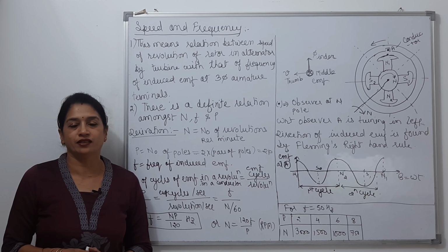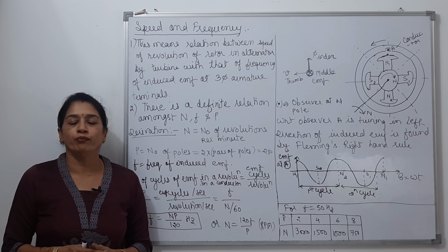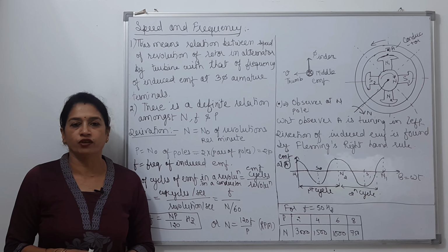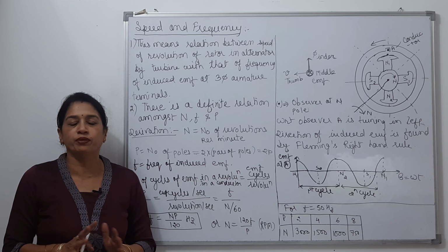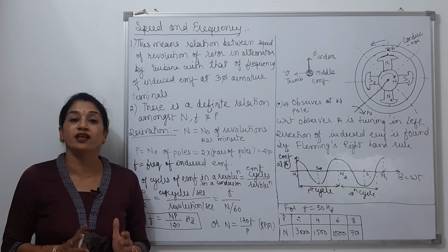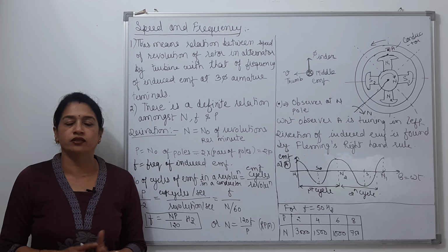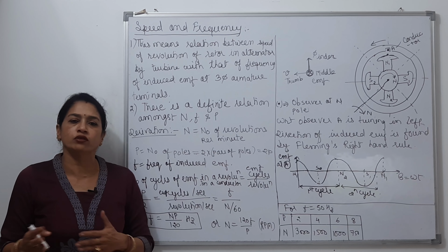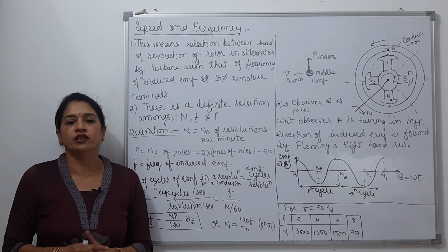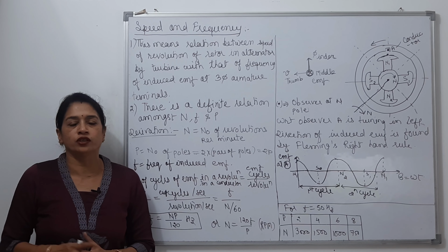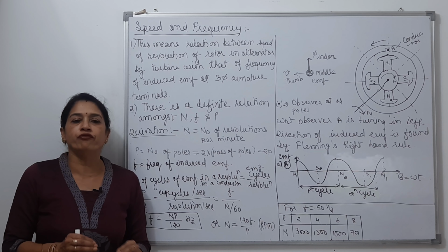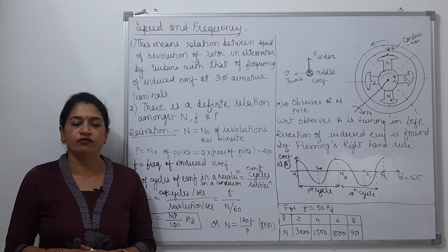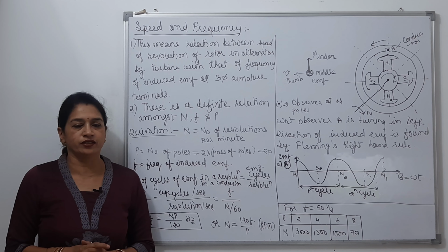Later I explained the reason why the three-phase armature winding is provided over the stator. That means we have to make it stationary and not rotary, as it would be if provided over the rotor. We keep it always over the stationary stator in large alternators whose capacity to generate power is in megavolt ampere. For those alternators used for the generation of power, we place the three-phase armature winding over the stator itself.